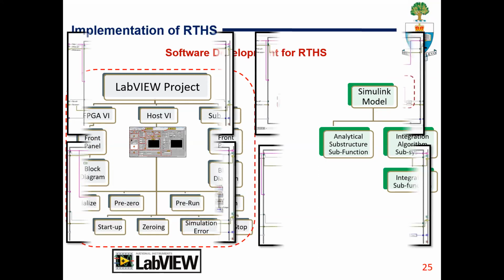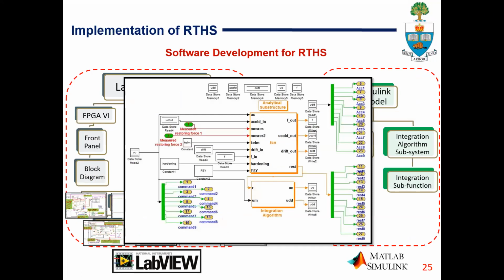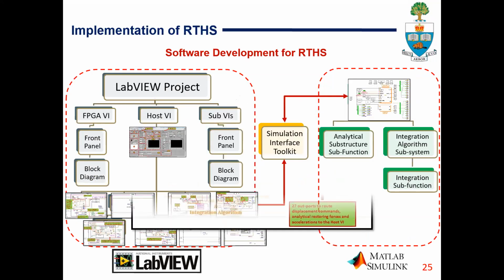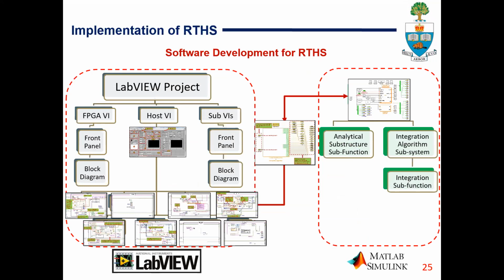And on the Simulink side, we have the model for the analytical substructure. And there is simulation interface toolkit where you can convert the Simulink model into an executable DLL and embed it in your LabVIEW model and run it from within LabVIEW.